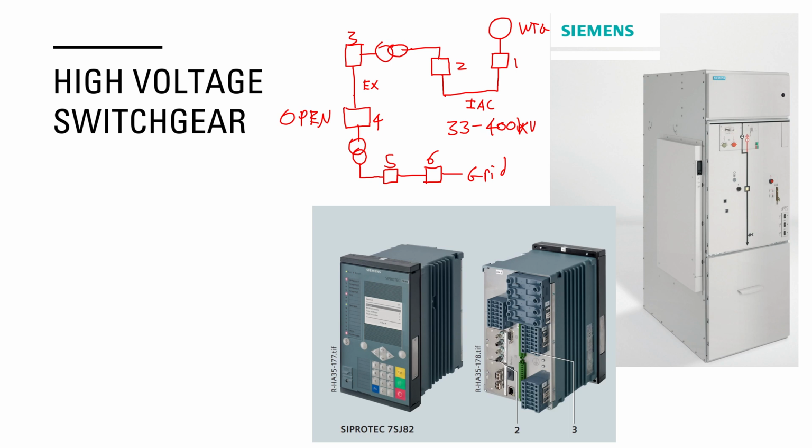And it does that using a mechanical system based on springs. So these are not relays, they are very heavy duty clockwork machines that operate on springs such that the switchgear can open no matter what, and it must be able to do that.